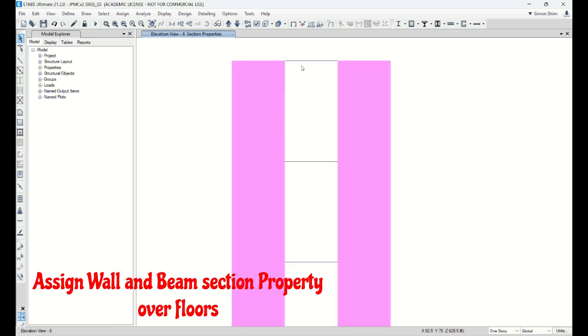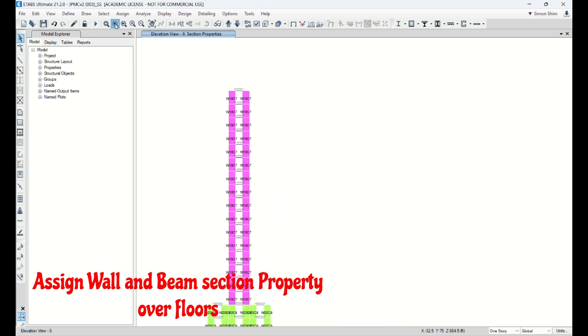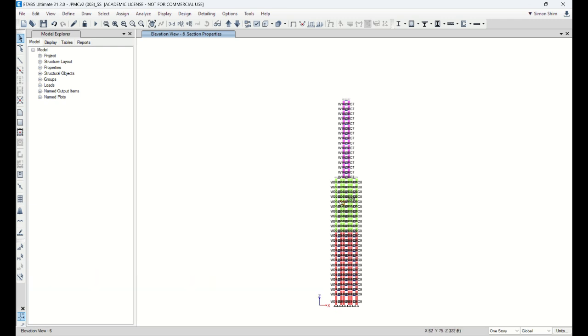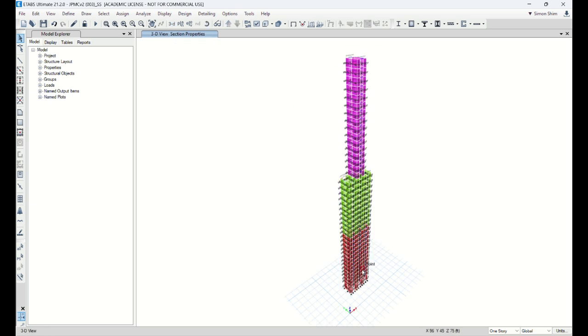All right, so first of all, I just somehow randomly assign the wall, define the wall section properties and link beam properties, but at least what I did is matching the link beam width to wall thickness. So this is the first random core wall profile I'm gonna use for first analysis. Okay, so let's see what I'm gonna get, especially for lateral deflection under the wind load in X and Y.